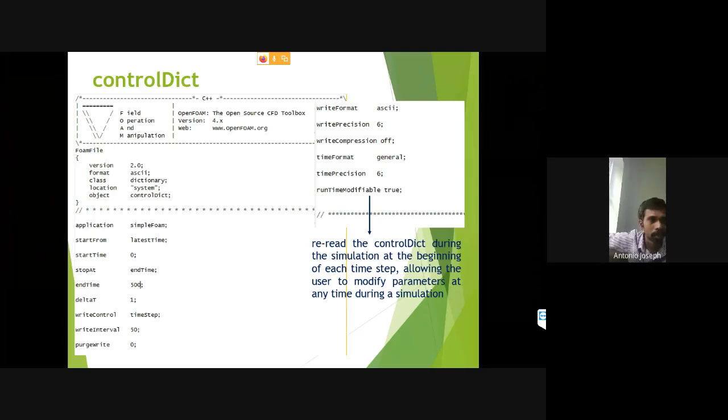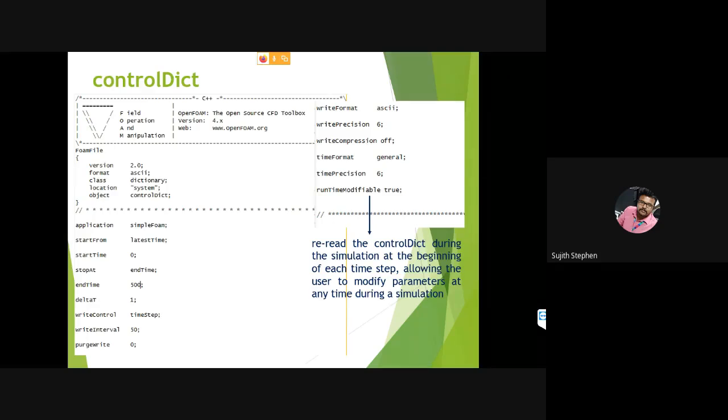Yeah, next question. One doubt regarding Courant number. Yeah, you can ask. No, sir, actually, I did two simulations, one in ANSYS Fluent with the PISO solver, and the other one in OpenFOAM pisoFoam. I used 0.01 as time step size in ANSYS, but the same time step is not working with OpenFOAM. The Courant number is increasing and it is exiting.